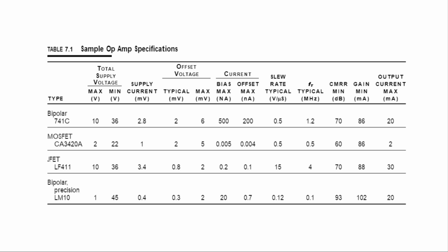There's also input bias current. Theoretically, an op-amp should have infinite input impedance and therefore no input current. However, small currents may be drawn in by the inputs. The average of the two input currents is referred to as the input bias current and can result in voltage drop across resistors in the network and can lead to errors in the output. Input bias depends on the input circuitry. With FET op-amps, input bias is usually small enough not to cause serious offset voltages, but bipolar op-amps may cause problems. With bipolars, a compensation resistor is often required to center the output.